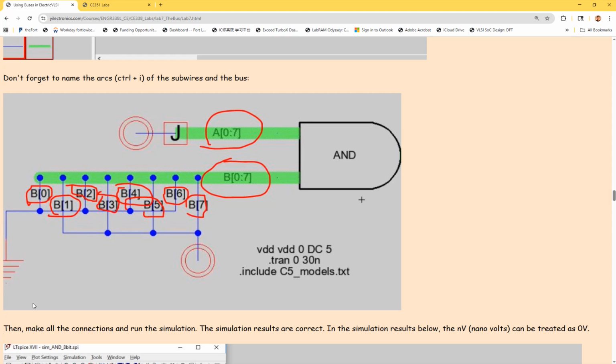So we don't really have to explore all these logic inputs. One way to do that is I just directly merged all the buses for the A input. Put a junction component over here, so it's gonna merge all the wires in the bus, and then I short everything to VDD. So I'm basically giving 1 to all the A's.